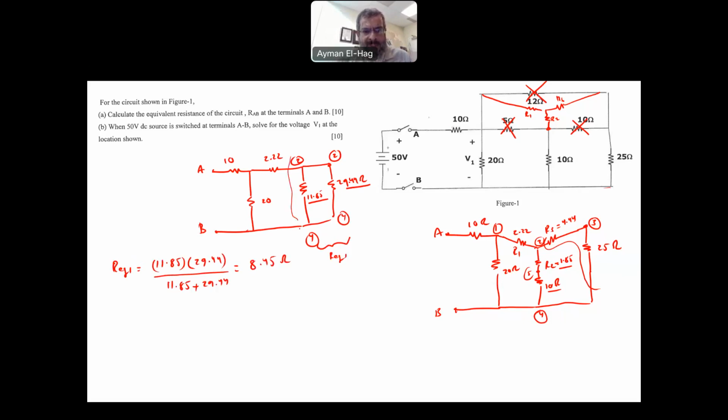So all of these resistors, now we can have as only one resistance. You redraw the circuit, and that is what I strongly suggest. Every time you do a reduction, go and redraw the circuit. So we'll have here 8.45 ohm. So this is node number 2. Now, when you add two resistors in parallel, the two nodes will stay the same. This will be between 2 and 4.